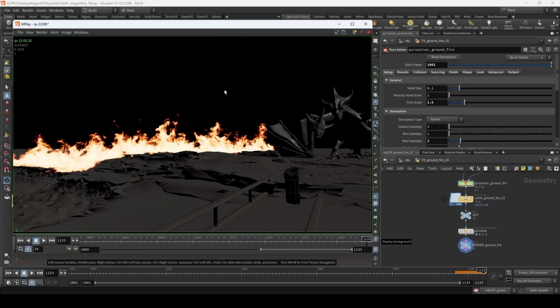And yeah, just one more note for this section is I've simmed it at a voxel size of 0.1, and it took about 5 minutes on my computer. So obviously this is really fast, and we can resim it at a voxel scale of 0.05 perhaps. And this way we'll get nicer details, everything will look sharper, and we'll probably get also more of these smaller flames. For next week, I will resim this, and that way when we work on the rendering, we'll just get an even nicer looking sim.